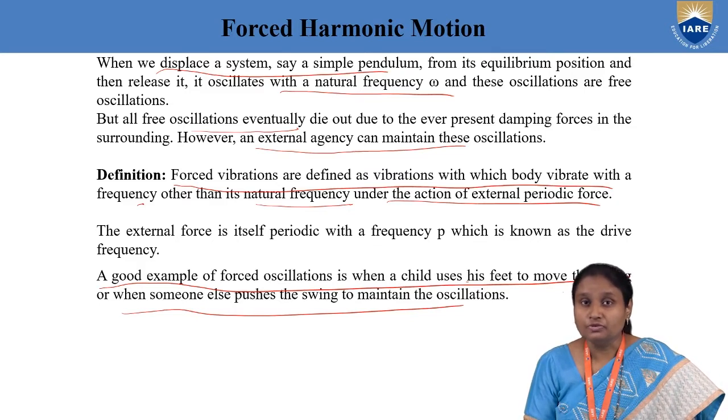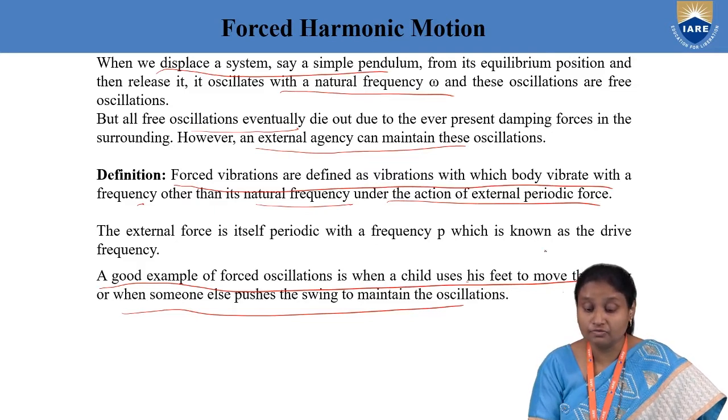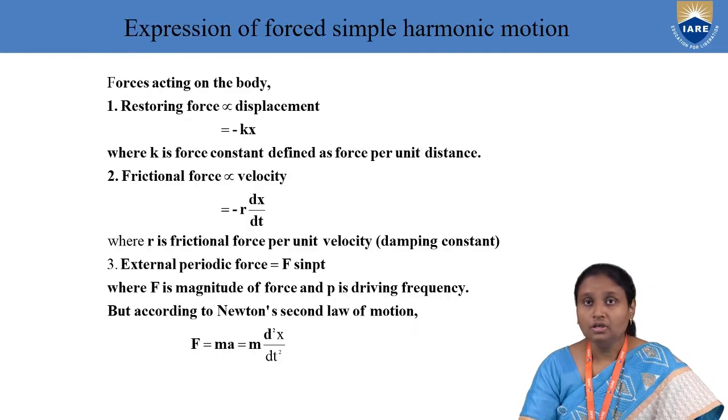And always for forced vibrations, we need one external force. And the frequency given by that external force is called the drive frequency. Usually it is represented by P. Now we'll try to get a second order differential equation for forced simple harmonic motion.